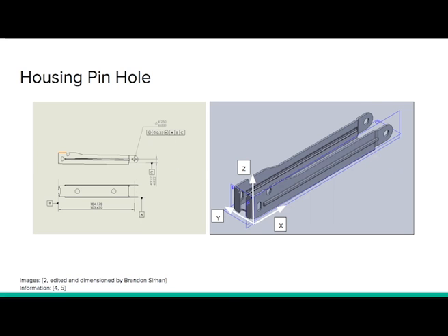To account for the capabilities of metal stamping and the cost of production, we tolerance the diameter to have a lower limit of 4 millimeters and an upper limit of 4.25 millimeters. This is justifiable for the location of the pinhole in the horizontal and vertical directions, as shown in the image here, with the horizontal positioning being anywhere between 103.67 millimeters and 104.17 millimeters from datum B, and the vertical positioning allowed to be anywhere between 4.922 and 4.422 millimeters.